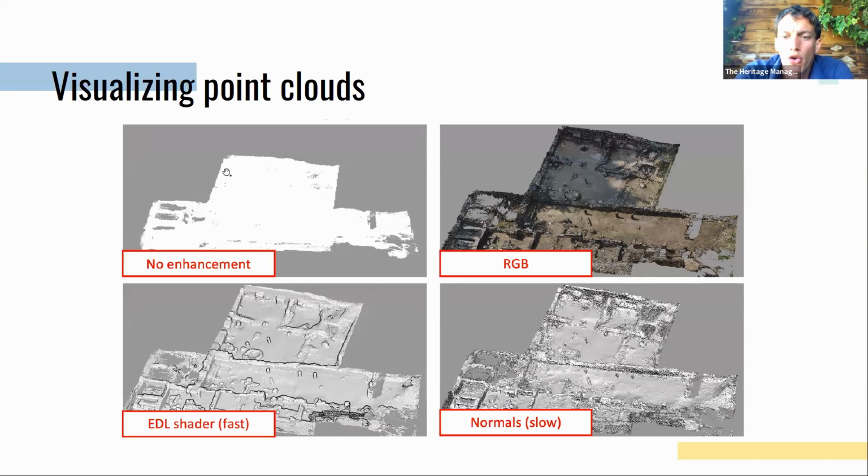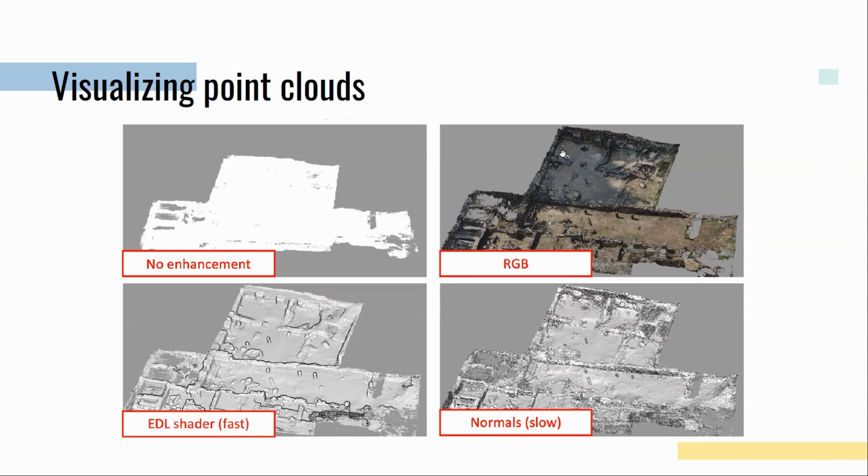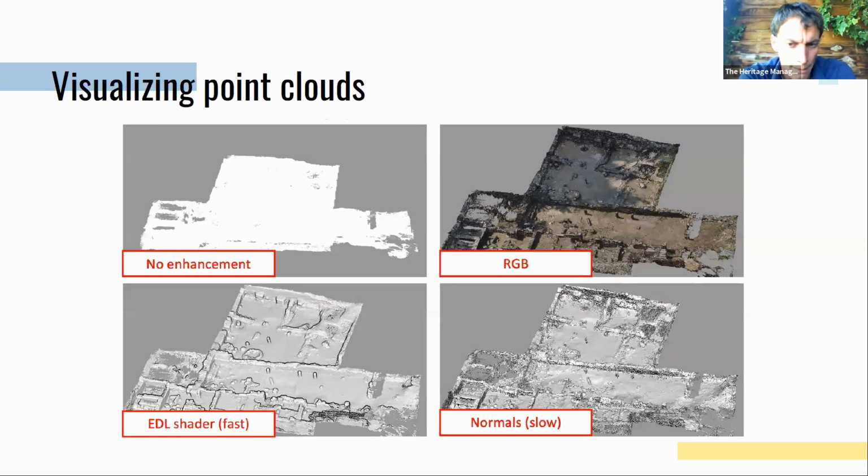So this is the normal hardcore raw data that you can acquire with laser scanning or with photogrammetry if you export your point clouds. And of course, in each and every point, so let's say that this is 15 million or 20 million points, each and every point can get an RGB value, so a color code assigned to each individual point, and that will allow you to distinguish certain objects in your point cloud. It will, at least in your mind, by looking at the point cloud, give you some kind of visual impression that makes it much easier to interpret the different clouds.